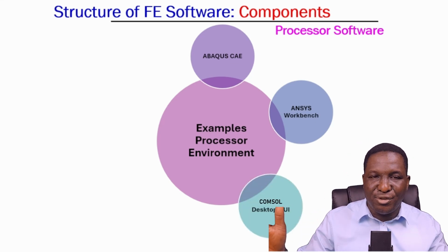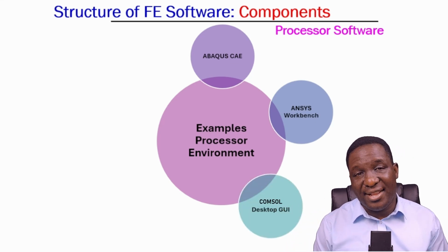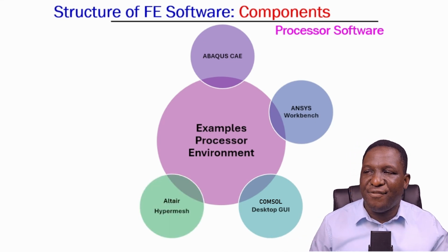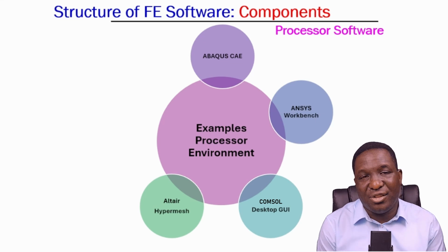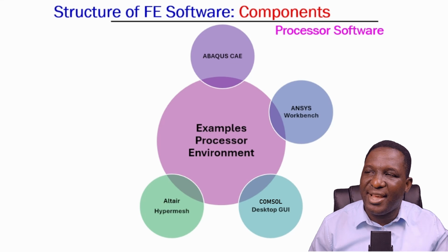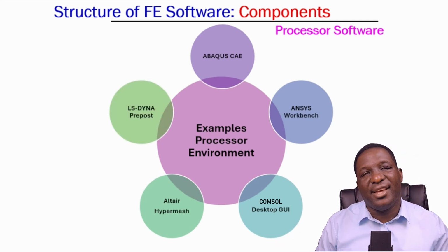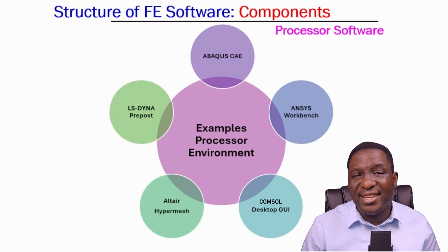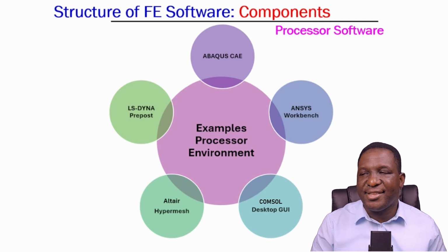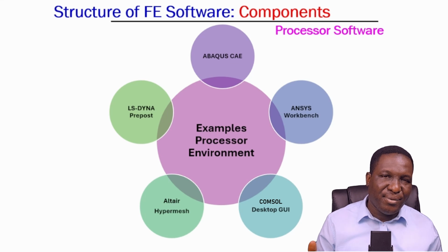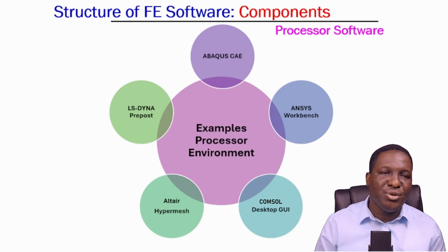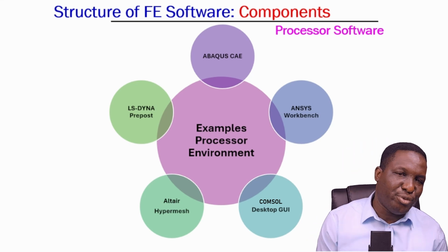So we also have COMSOL, which is another finite element solver, and it's got a graphical user interface called the desktop GUI, which is also a preprocessor environment. Altair HyperMesh is again another powerful software tool, and it's got the HyperMesh environment that allows you to pre-process. And then finally, LS-DYNA is again a finite element solver that is particularly targeted at impact behavior of systems, crash absorption, crashworthiness tests, and it's got a preprocessor called PrePost, which is a dedicated software by itself that helps you pre-process the model and also post-process the model.